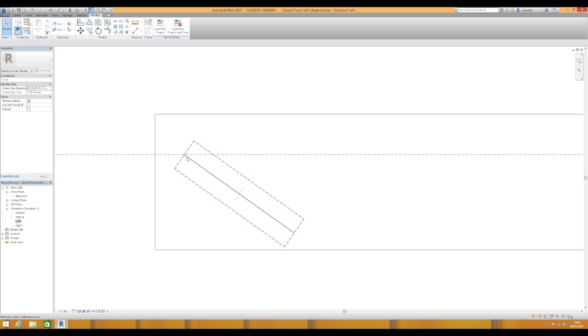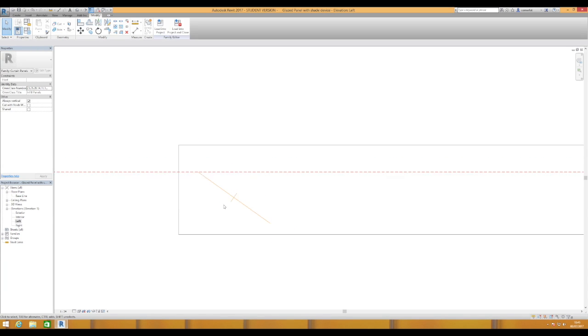The reason is there is available a louver blade, a nice curved aeroplane wing shaped louver blade that is 150 millimeters long and 18 millimeters wide. So that's just setting up some geometry for me to let me create a louver blade. So I might create that first louver blade.